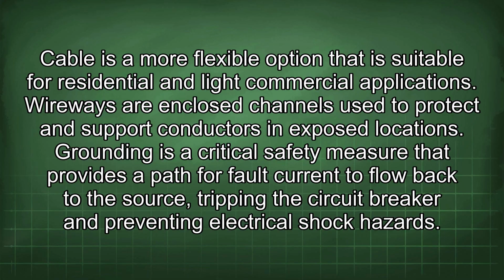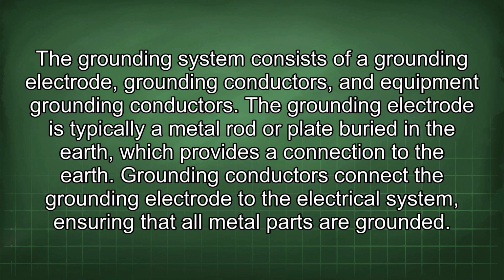Grounding is a critical safety measure that provides a path for fault current to flow back to the source, tripping the circuit breaker and preventing electrical shock hazards. The grounding system consists of a grounding electrode, grounding conductors, and equipment grounding conductors.